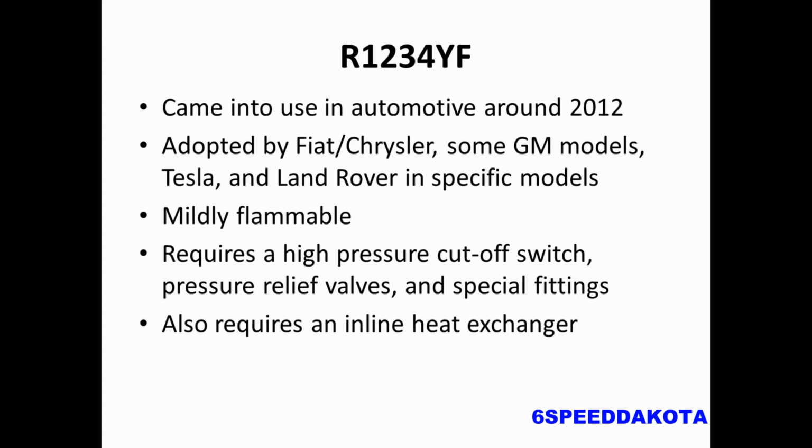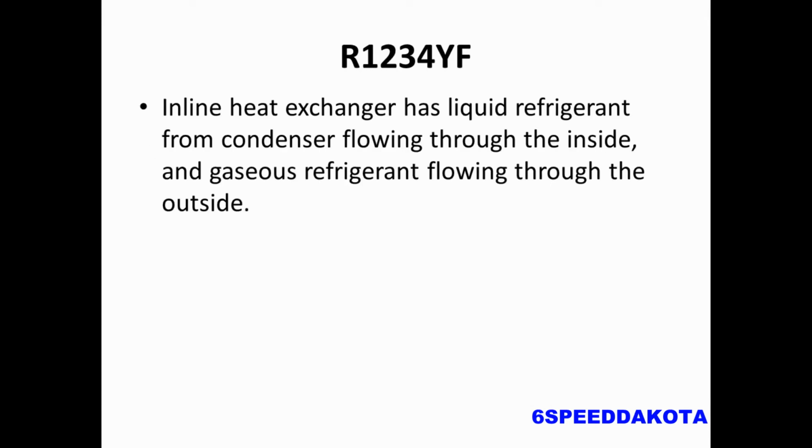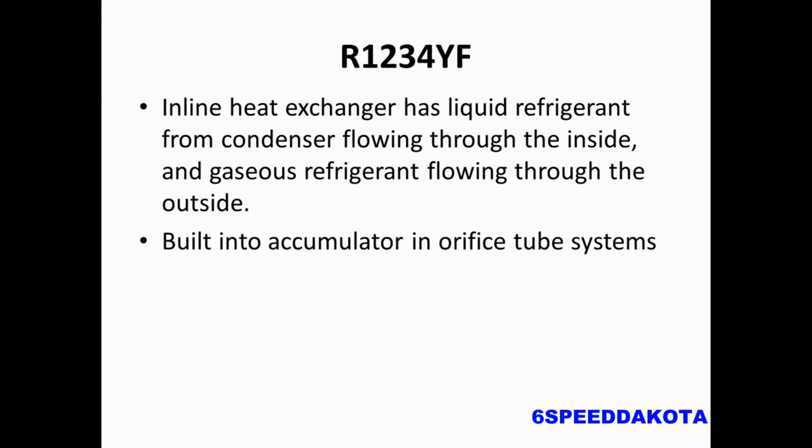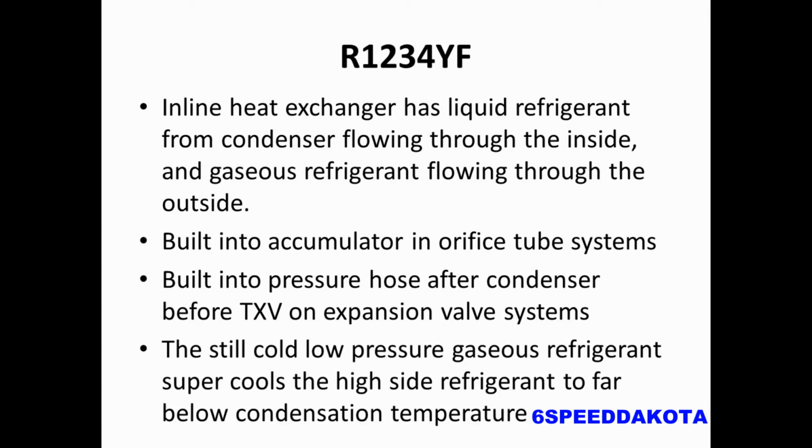This also requires an inline heat exchanger. It's slightly different from a normal system. This stuff is very expensive and makes it infeasible to convert an old R134A system to 1234YF. The inline heat exchanger has liquid refrigerant from the condenser flowing through the inside of the heat exchanger and the gaseous refrigerant flowing through the outside. It's built into the accumulator on an orifice tube system, and it's built into the pressure hose after the condenser before the TXV on a TXV system. So the still cold, low pressure gaseous refrigerant supercools the high side refrigerant to far below condensation temperature.